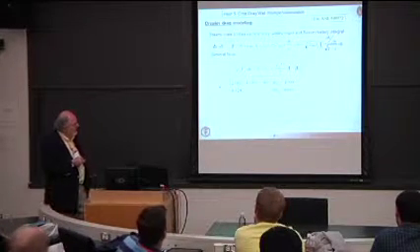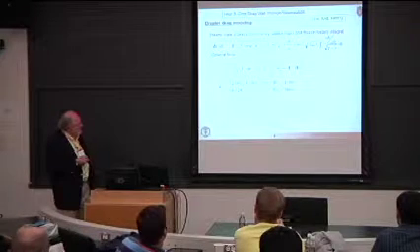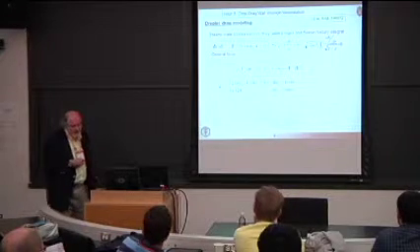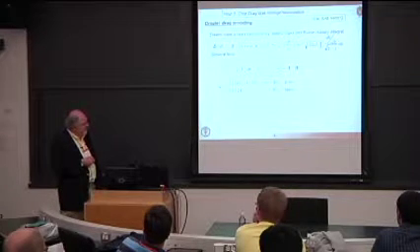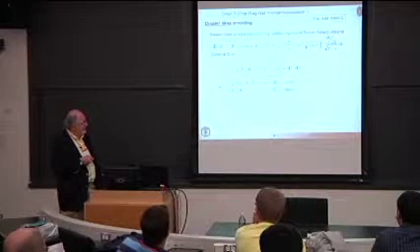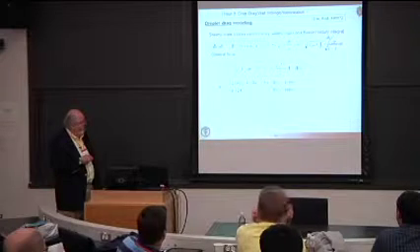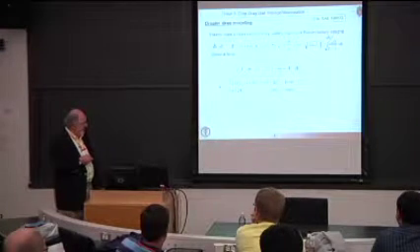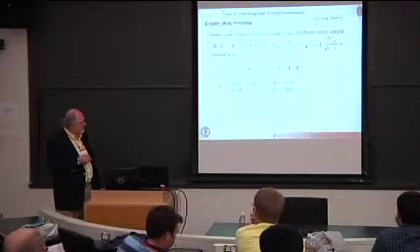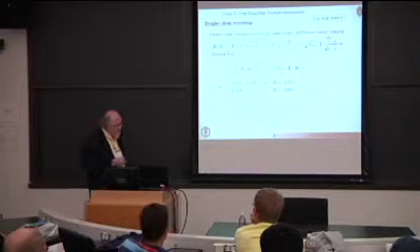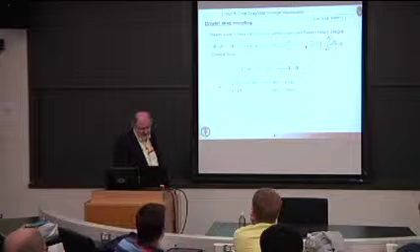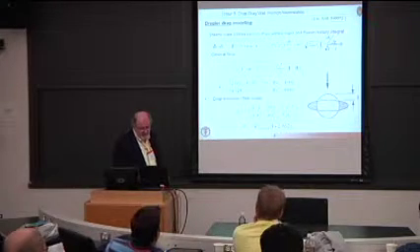So we need a drag coefficient. And literature on drag around spheres shows that there is a region where Stokes drag is applied at low Reynolds number, that's 24 over Reynolds number. And then for high enough droplet Reynolds numbers, the drag coefficient is taken to be a constant. So that's the way this is implemented in, say, the original Kiva code.